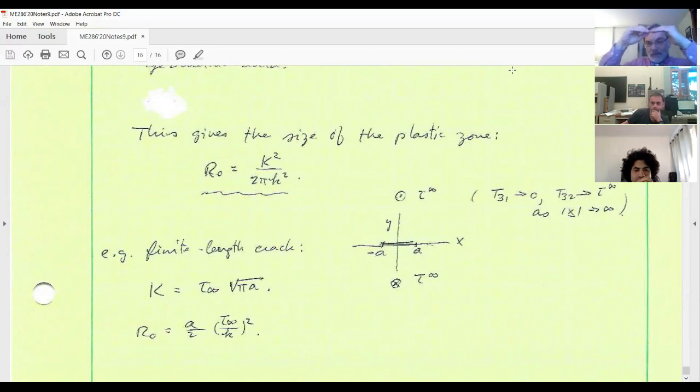The crack tip won't be on the boundary. It'll be interior to the elastic plastic region. That's a substantially more difficult problem, and you can find some research papers on that. So we made no assumption concerning the shape of the boundary between the elastic and plastic zones.